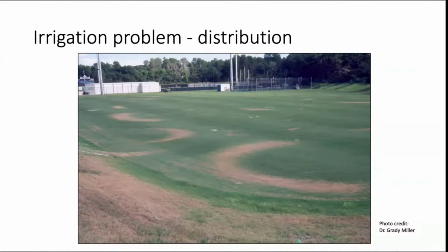Well, to me, this is pretty obvious that either it was insufficient pressure and that didn't throw far enough, or the designer put the sprinklers too far apart, or incorrect nozzles, or any combination of that. That, believe it or not, is not too unknown. I've seen a number of wastewater irrigation systems where they just want the circles touching. That is not what we want. We want them to be overlapped.